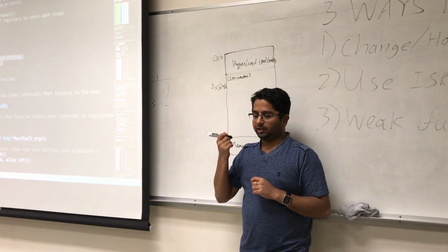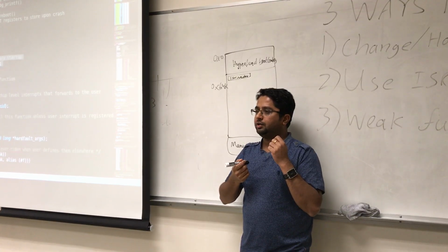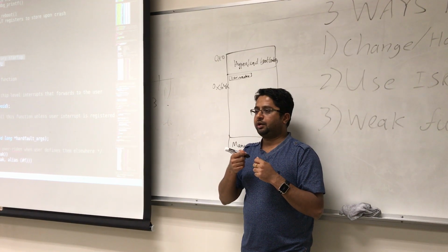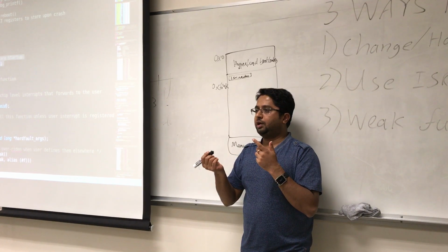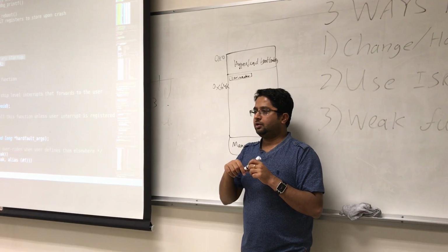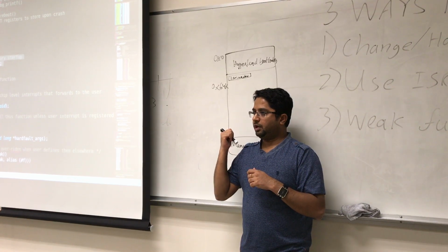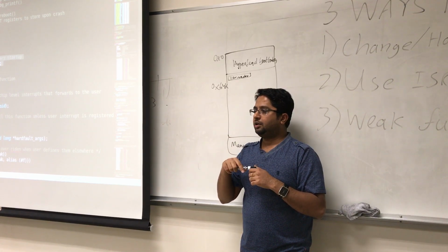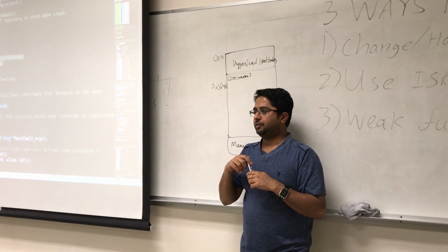There's something called function name mangling, where in C++ you can have different source codes with the same function names, and the C++ compiler mangles them to make sure that everything gets compiled and only one of them runs depending on how it resolves it. So similar to that, when you write the interrupt handler function in your code, since most of them are .cpp files, you will need to add the keyword extern C. Okay?